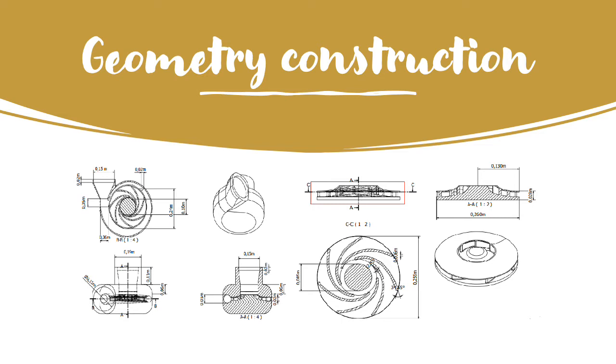Important tools required in this creation are elevation and extrusion between planes. During the creation of the casing, it is important to take care of some dead zones that could create high stress. Finally, an ensemble must be created by the combination of the impeller and the casing. The isometric planes of the pump created in Autodesk Inventor are shown in this slide.